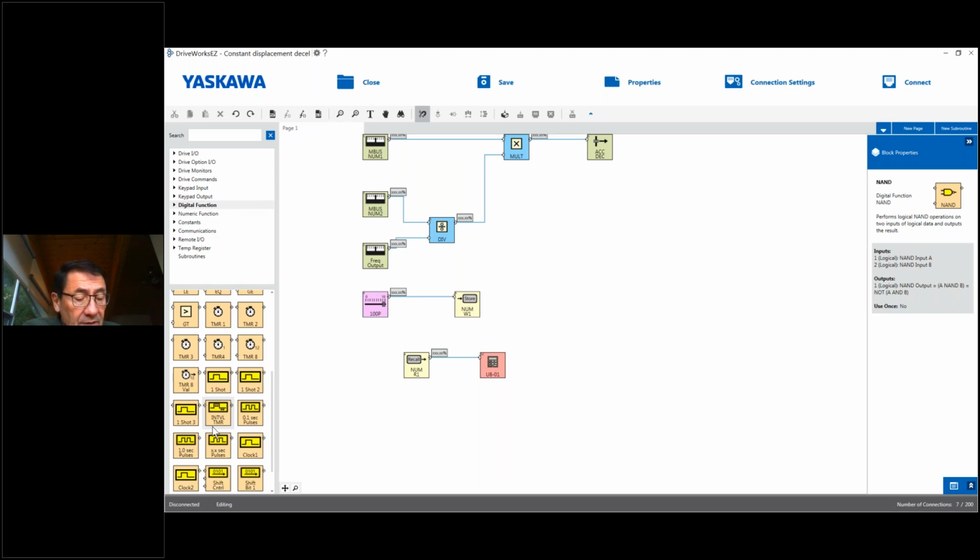Nevertheless, the point here is that that signal will go away, but we want to affect a permanent change that's not time related to the signal itself. And so we'll need to do some sort of latching logic or one shot in this program. I haven't solved that portion of the program yet, but that may be one of the tools that we use.